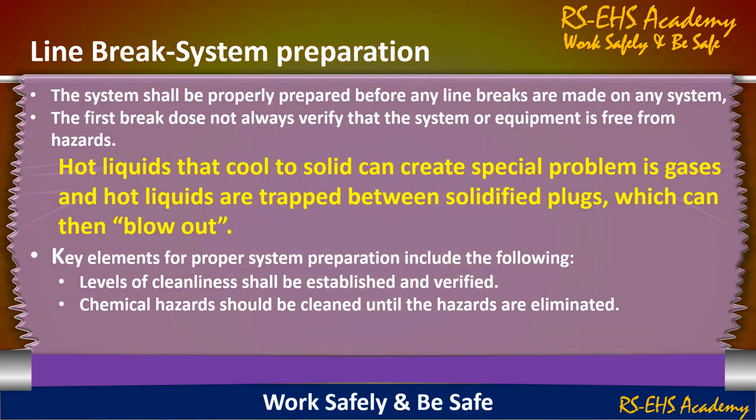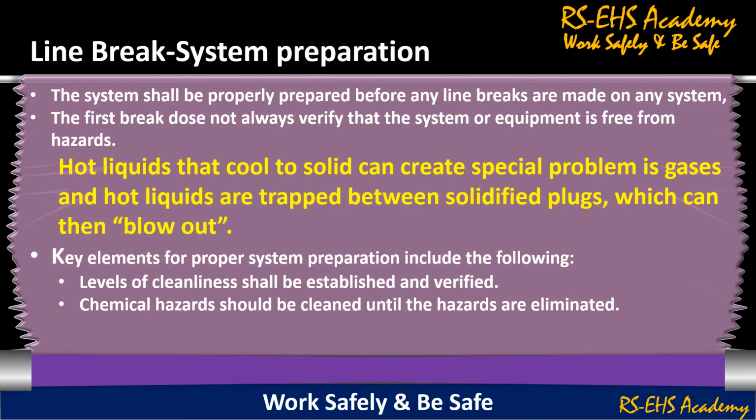Line break system preparation. The system shall be properly prepared before any line breaks are made on any system. The first break does not always verify that the system or equipment is free from hazards. Hot liquids that cool to solid can create a special problem with gases, and hot liquids can be trapped between solidified plugs, which can then blow out.